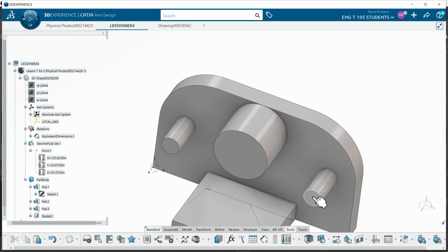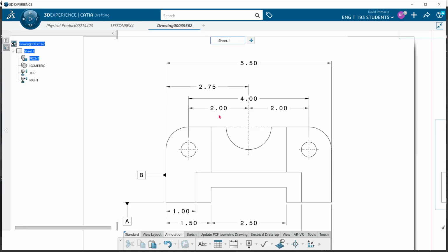But the other shop builds it at 1.97, 1.97. That would mean that the distance from this pin to this pin would be 3.96. And back to the drawing, if they had made this part at 2.03, 2.03, you're looking at 4.06. So now again, you're off by 0.12 or 120 thousandths of an inch between your pins and your holes.